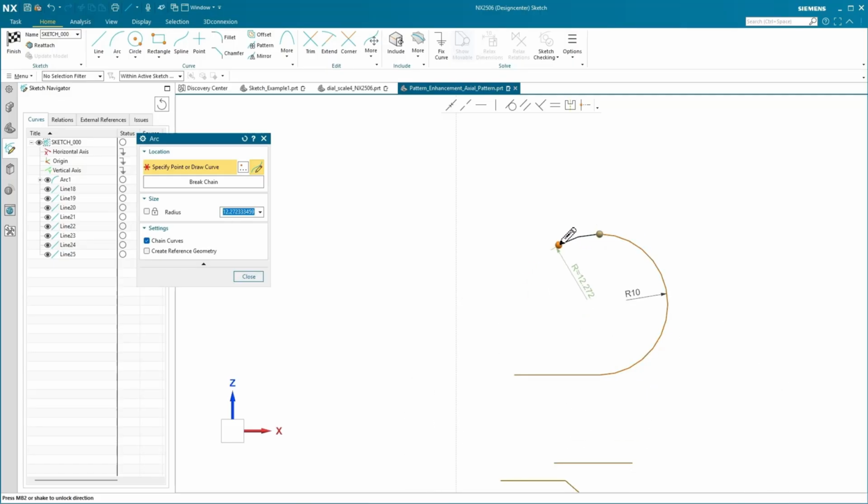All right, so that's how you can create the tangent arc off of the previous arc there, or if it was a curve, off of a linear curve. So just put your cursor back over the previous node or the start node for the new arc, and then you can come back up and create what would be almost like a perpendicular off of the previous endpoint.